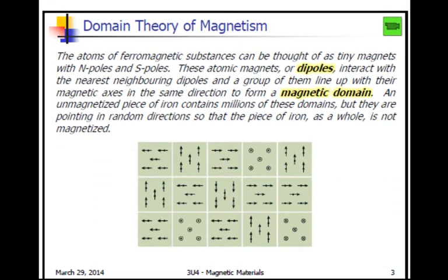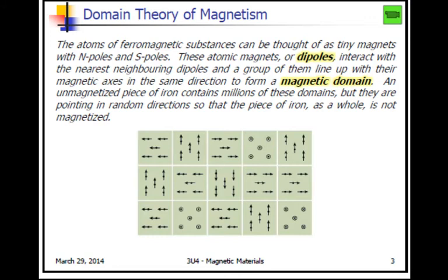So what's happening with a soft ferromagnetic material? Well, what's happening is we're organizing the magnetic dipoles that exist inside the material. So if we consider a magnetic dipole, let's say we have little sticks of iron inside of a material, and they could be oriented in a whole bunch of different ways.